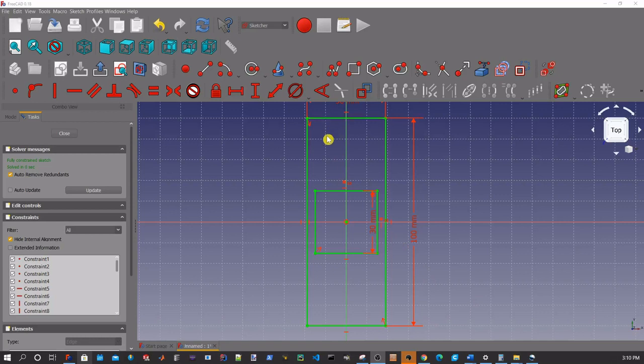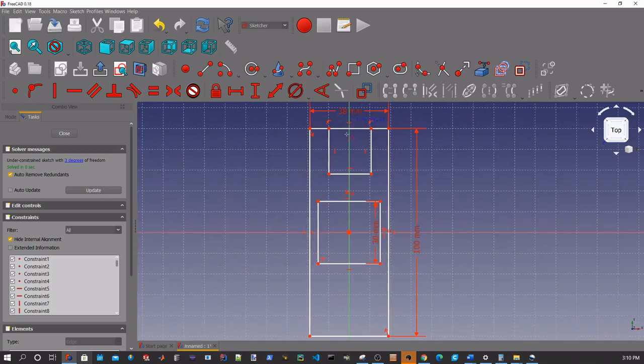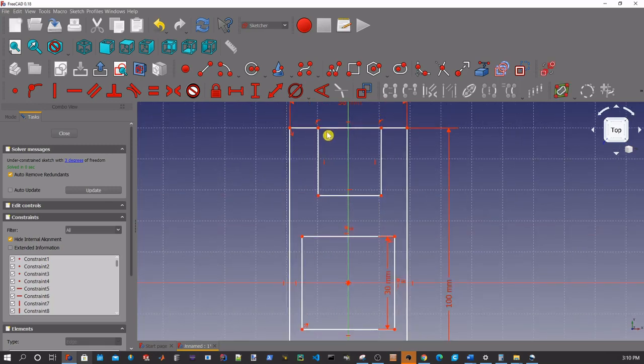Next, we'll cut out an area up here for our top plate to place the camera, and we'll do that by selecting the polyline tool. Make sure we get that constraint to fix onto that top horizontal line. We'll just make a quick cut out here. Now we can easily get rid of this area here by coming up and selecting our trim tool. It's got the perpendicular lines like a T with the dotted line coming out the top. If we select that and click right on that middle portion there, it'll trim it right out.